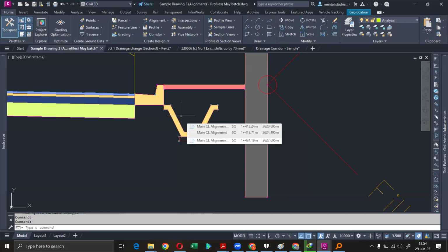I think that is the Kulambiro Ring Road. I don't know if you've passed there before. These guys have an open gutter, and they designed it very well. Below the open gutter they have culverts, but those culverts are deep, so they're not near the surface. They want the water to collect, then they push it deep.